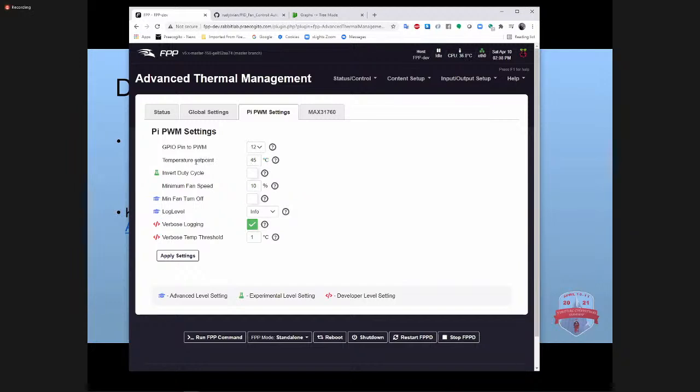And the temperature set point that you'd want to set is the target threshold. What that means is it's essentially using a PID loop to control that. It's a control algorithm that basically targets that temperature not to exceed. So as it approaches that temperature, it'll increase the duty cycle, or the on time effectively, of your fan, so it would cool things down before it reaches that temperature.